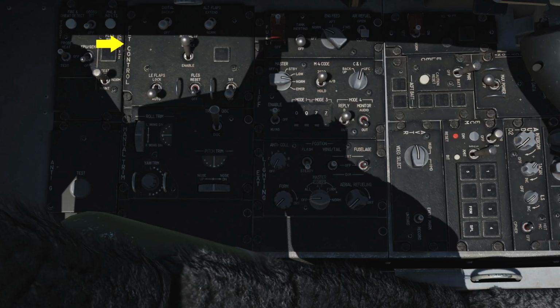To the right is the flight control system panel, and as you might imagine, this panel allows you to set manual controls of the F-16's flight control system. Now, normally you don't have to touch these very often, as the Viper's flight control system is highly automated. The digital backup, or DBU switch, selects the FLICUS backup software. If enabled, you'll see a DBU caution light and a HUD warning. This would rarely be used though.